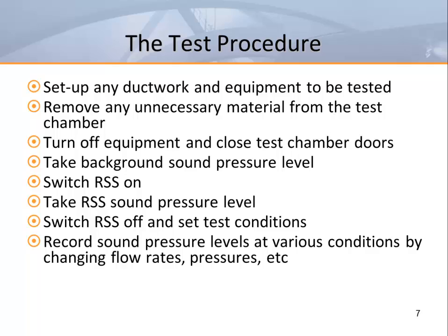In order to get meaningful results, there's a procedure that must be followed during the sound testing process. First, we must set up all the ductwork and equipment to be tested. Any unnecessary material should also be removed from the test chamber because everything inside the chamber will absorb some amount of sound energy. Material must not be moved in and out of the chamber between test runs, as this will change the room attenuation each time it occurs.